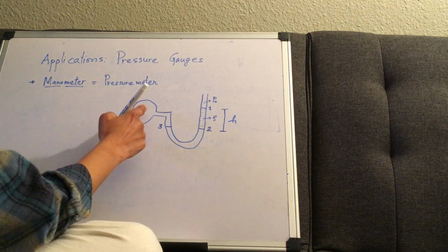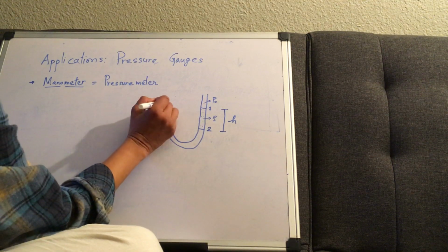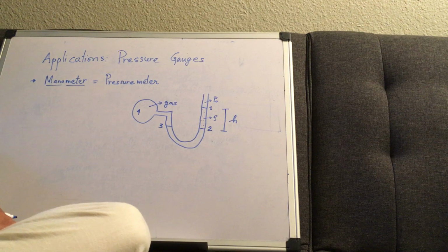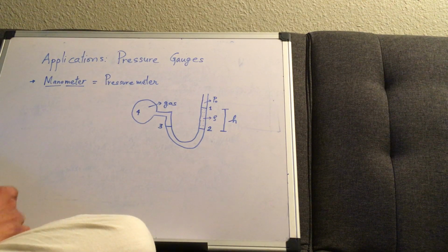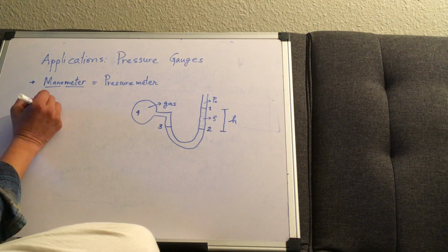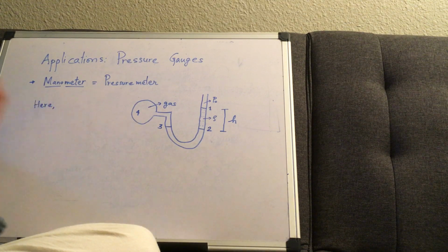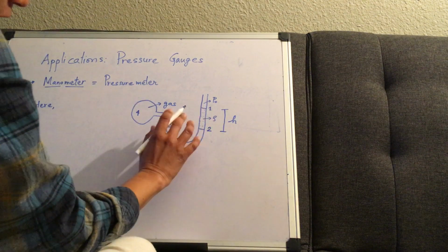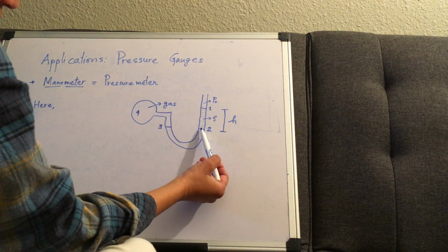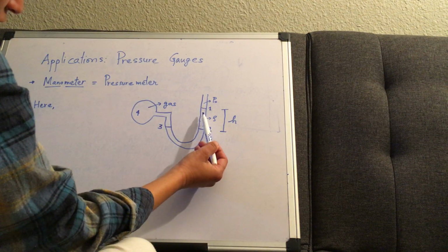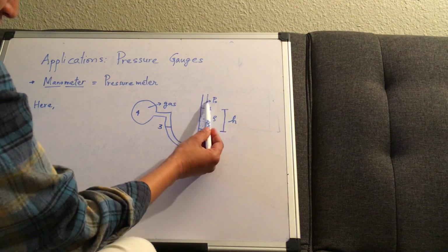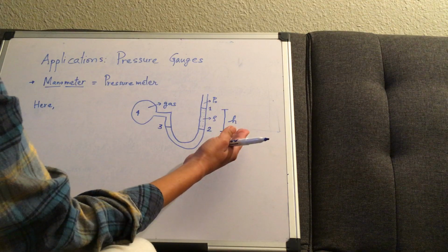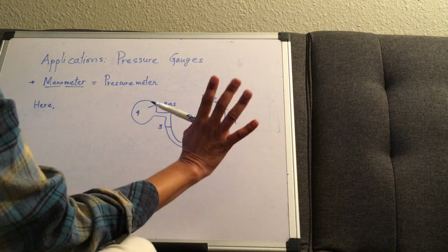This other part is filled with gas. Can we find the pressure here? There is this fluid at a height h, and there is atmospheric pressure. You should be able to find it using the hydrostatic pressure equation, because this fluid is not moving.